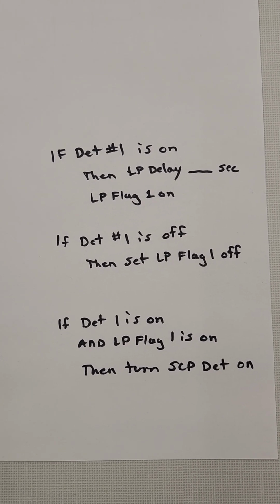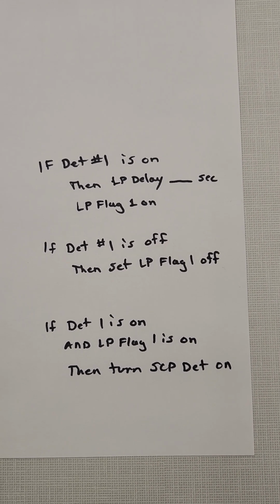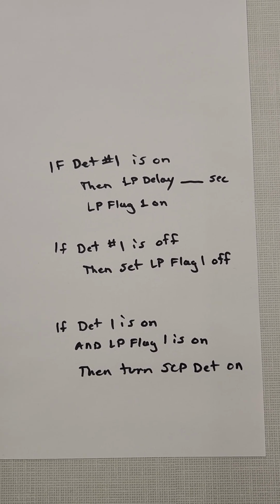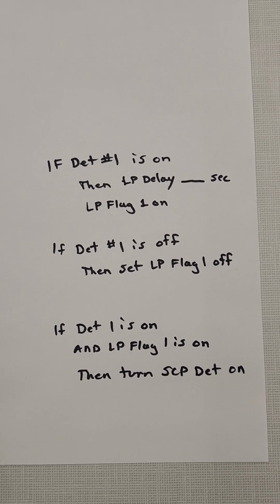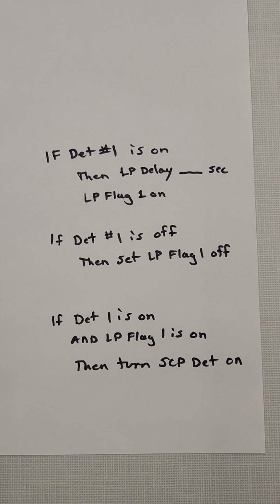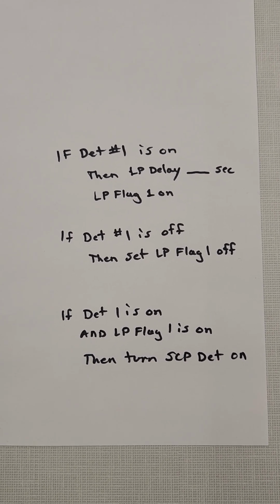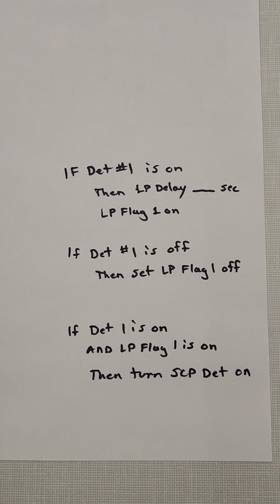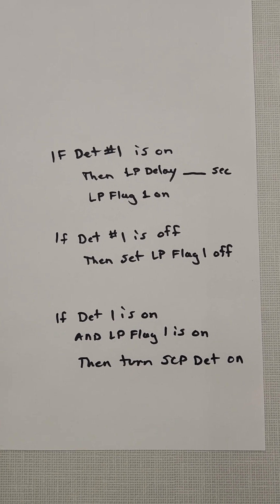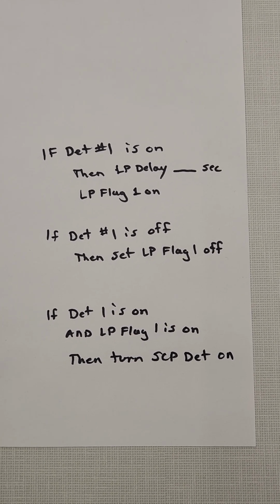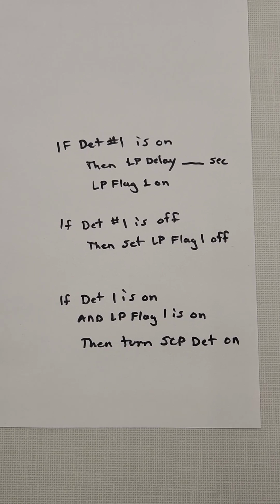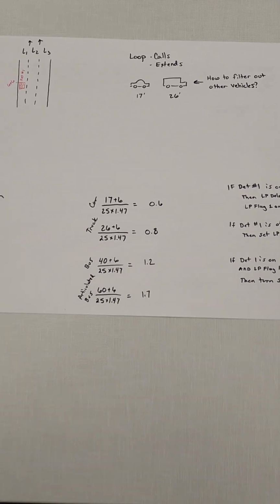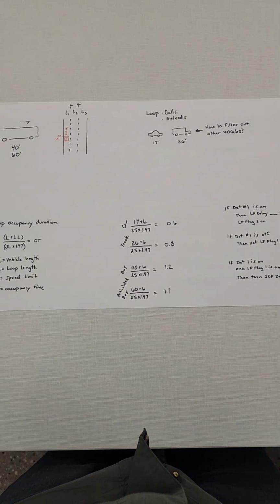And that, in my experience, has worked pretty well for pretty low-tech solutions. It's just a good way to get a low-tech signal priority system up and running without spending too much money on AI-based video or radar or LiDAR detection or some centralized system. Just a really quick way to use low-tech solutions to get your TSP running.